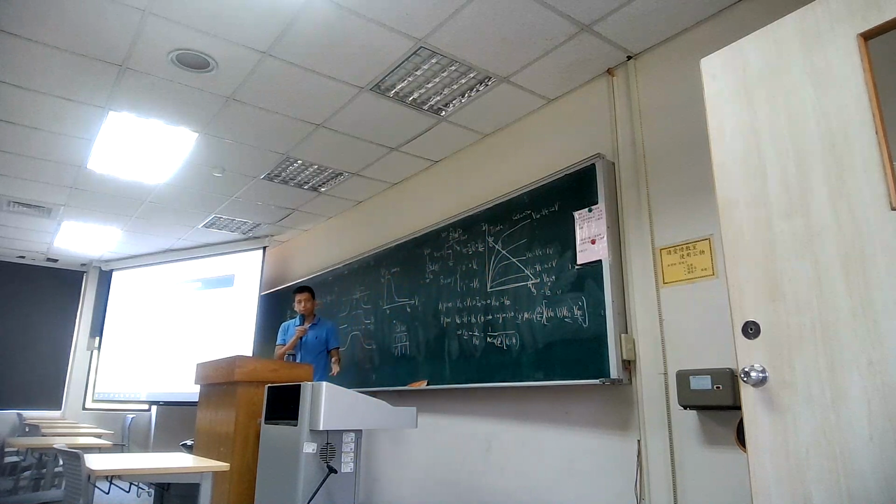And this triode region gives you current flow and brings down the VDS. This VDS represents the output voltage. And for this output, its voltage is typically low, typically 0.2 or 0.3 volt. Right? So that is the regular operation for all of these devices.